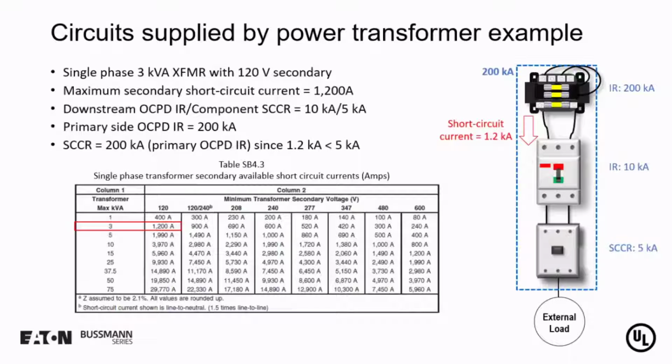So you can see that using fuses in a feeder circuit is an excellent means of increasing the short circuit current rating of all branch circuits supplied by a feeder. And I'll turn this back over to Dan to show you how this is accomplished.